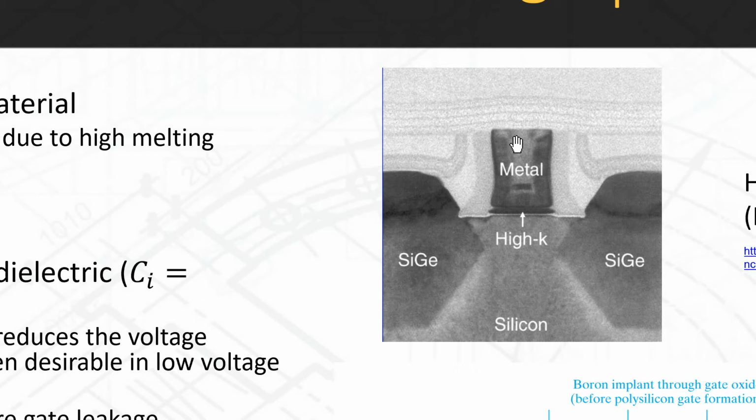If you have 1 billion transistors and you're trying to make the right connections and you want to make sure that your metal lines never cross over each other, you don't just need 2 metal layers. It turns out you need like 4, 5, 6, 7, even more. I don't know exactly how many metal layers they use in the high-end microprocessors today. Typically, a lot of that metal routing is done through computer algorithms. So those are like wires then? They're essentially wires, yeah.